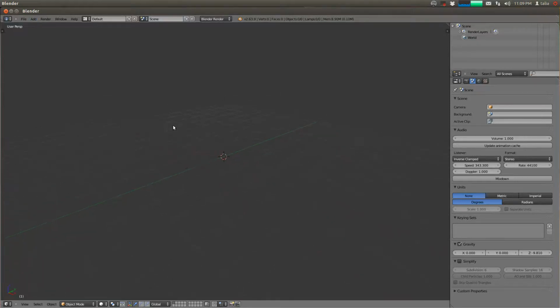I want you to notice that there's this grid in the middle of the viewport, right? I also have this little crosshair right in the center. That crosshair is known as the 3D cursor. I can reposition it by left-clicking at points in the viewport. Now, you'll note there's a distinct problem with working with a 3D cursor. No matter where I set it, I can't control how far back in space I'm setting it. Like, I can't control the Z depth from my viewport.